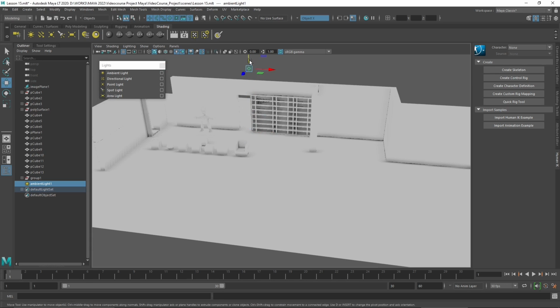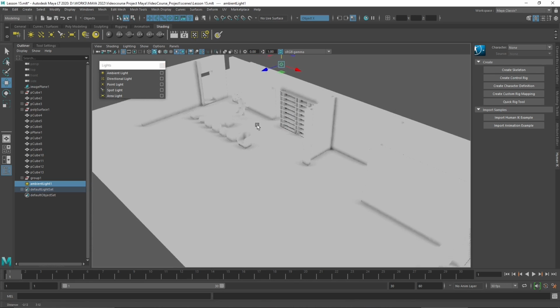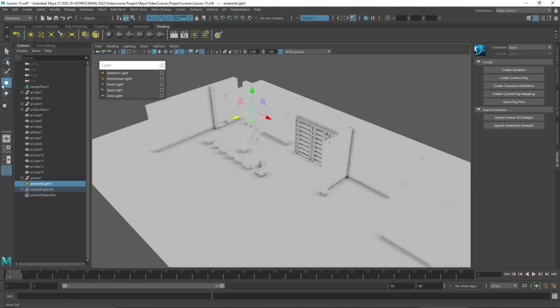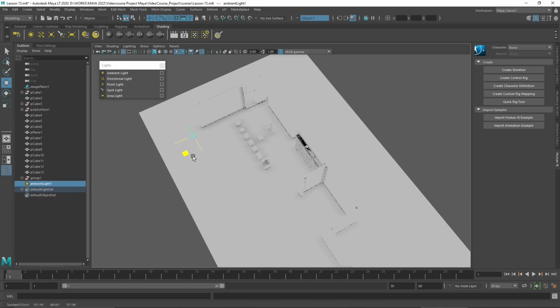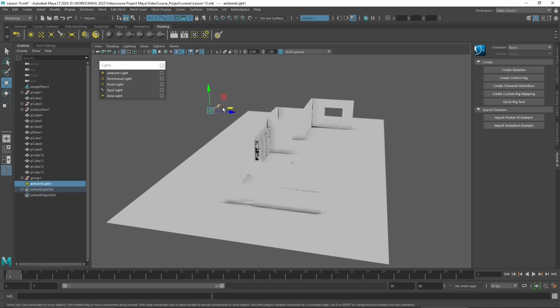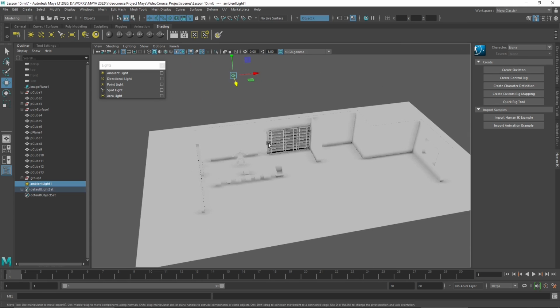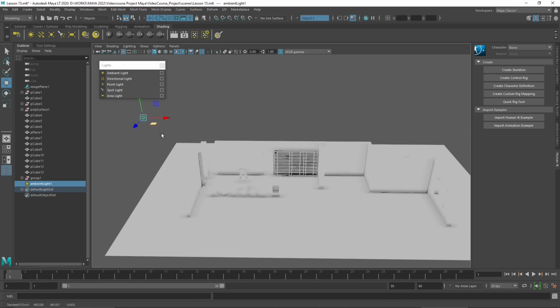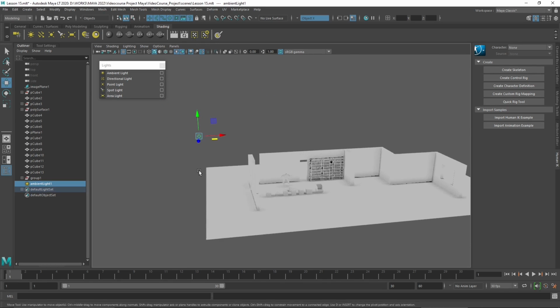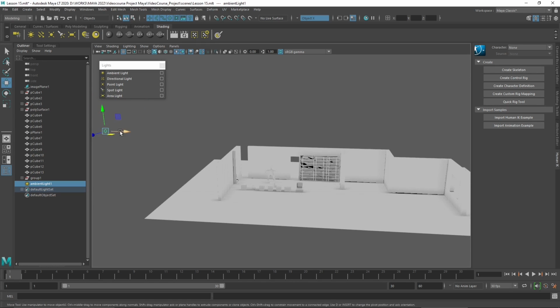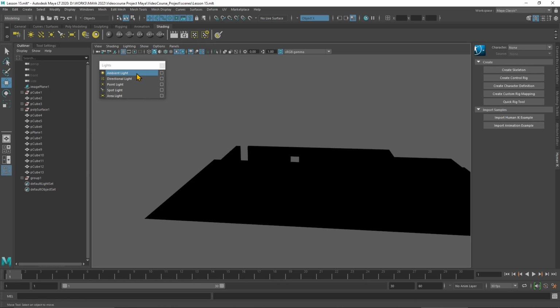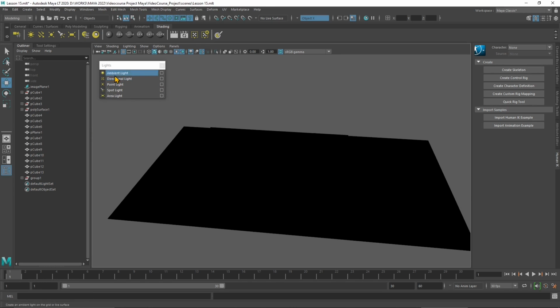Now this is pretty close to what we have, which is the default lighting or flat lighting. You can see it's a really soft and generic lighting that is going to light up the scene with a simple color, and that's the icon there. You can move it anywhere. This is not to be positioned somewhere in particular. You can position that anywhere. The effect will stay the same, and the shadows that this light produces are going to be kind of soft shadows and really not focused, because this is not a focused light, it's an ambient light.